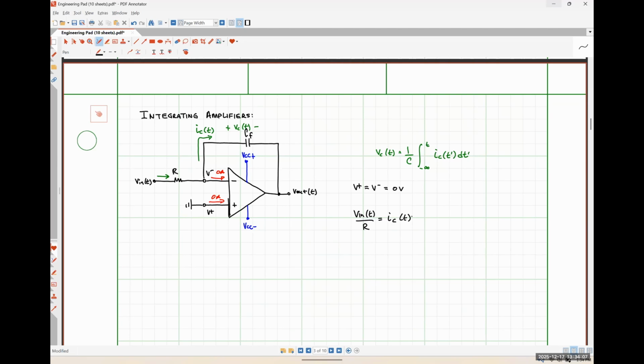So we have a little bit of a problem here, in as much as every other time we've applied KCL at our inverting input node, we've had a term for V out, and we don't have one in this case. So we're going to have to get a little bit creative here. I'm going to draw something here to kind of help us figure some things out.